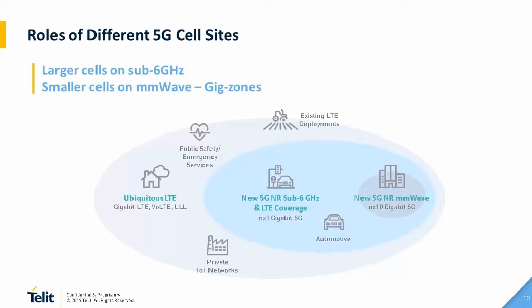And in terms of capacity, the way the spectrum is allocated, the lower frequencies, which travel longer, are much narrower, so the operators have less spectrum bandwidth available. Whereas as you go higher and higher in frequency, since they are not really used that much, especially the millimeter wave, which is very ultra high frequency, it travels a shorter distance, but it can carry a lot more data because the amount of spectrum available is much, much wider.